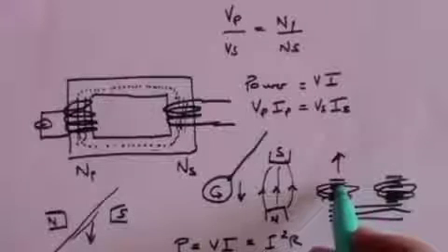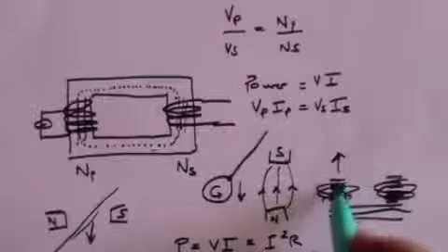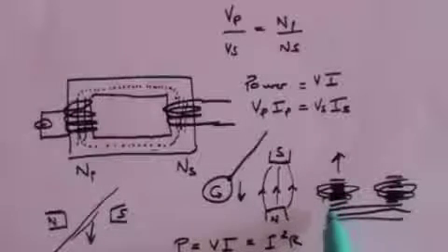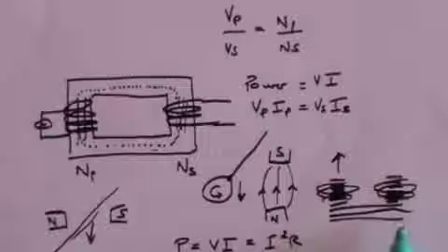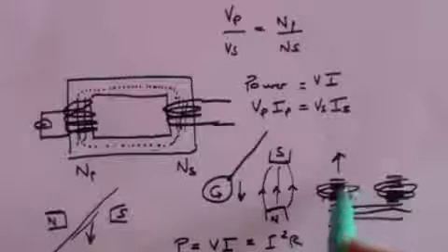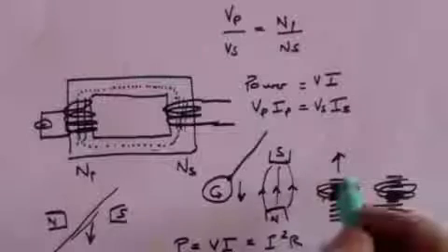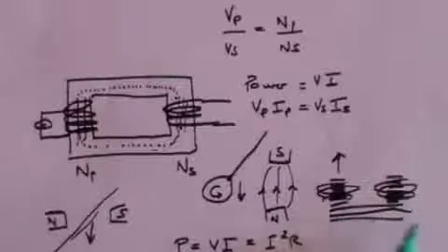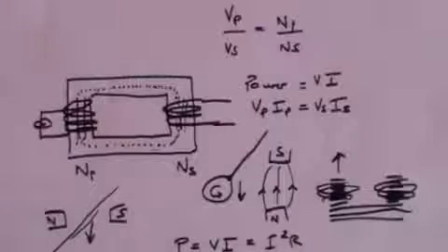And so consequently you can restrict the extent of the eddy currents that are flowing by having layers of iron separated by insulating material, but you can never stop the eddies altogether. They will flow in the layers, they just can't flow between the layers. So this is a way of reducing but not eliminating power loss in a transformer.